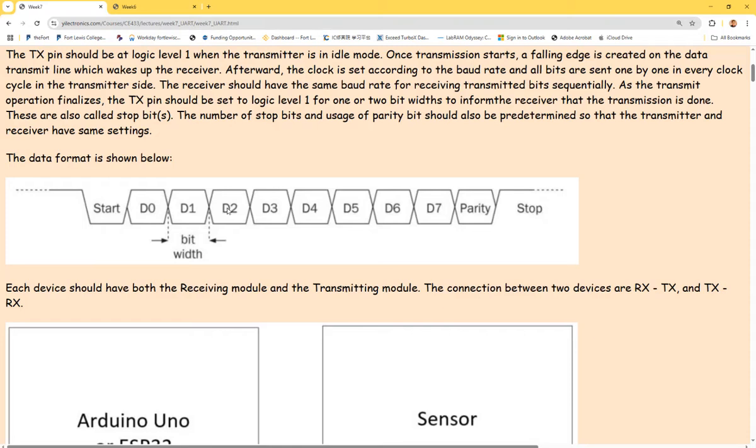I have it. So question number 2, for 9600 BPS, BPS means bits per second. Okay, that's the baud rate. We'll call it the baud rate for UART. And so what is the bit width? 1 over, yeah, it's 1 over, right? It's super simple. It's 1 over 9600. All right. So you'll know that this duration takes 1 over that baud rate.